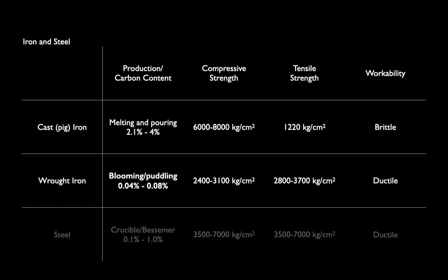If, on the other hand, you've got a bubble in a tensile element, when you apply more load than the resulting section can take, obviously the column or the tensile element is going to fail, and it's going to fail catastrophically. So the trade-off in cast iron is that it's extremely strong in compression, but actually dangerous in tension.